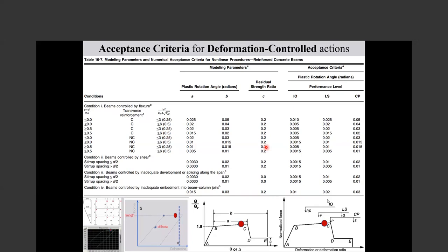So there are methodologies that you can apply to extend pushover analysis to the cases where ordinary pushover is not applicable. But the point is, for research, we can do it. For real life, usually the peer reviewers, the controllers, ask for the code provisions, not the research type of methodologies.